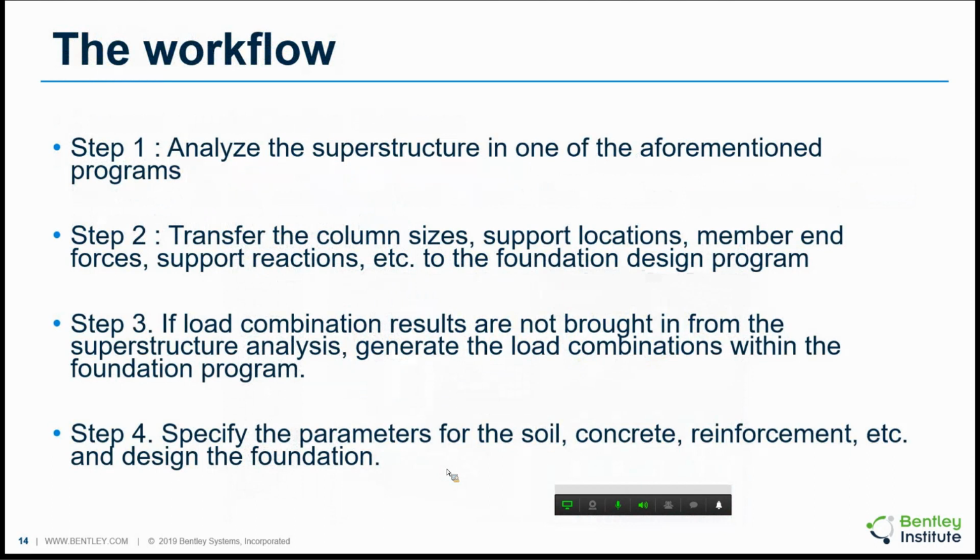Okay, so now that we have some of these programs in the portfolio, what is the workflow involved? As I said earlier, we have some programs that are for the superstructure analysis and design, and some programs for the foundation analysis and design. So we start with the model in the superstructure analysis program. You define your model, define your member properties and the loads and the steel and concrete design parameters and so on. And you analyze the structure in a program such as STAAD.Pro, MicroStran, RAM Structural System, and so on.